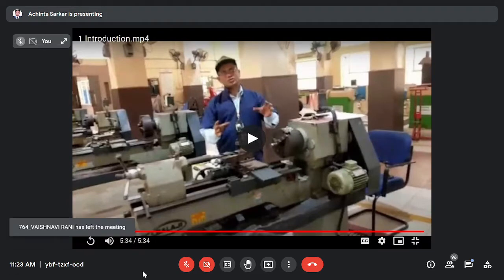Then the speed gearworks has such an arrangement that we can change the RPM of the chuck. As the chuck is attached to the headstock or gearworks, we can change the RPM there by manipulating two or three levers in that speed gearworks. We have to manipulate those gear positions to achieve different RPM. Different RPM is also required for cutting different materials.